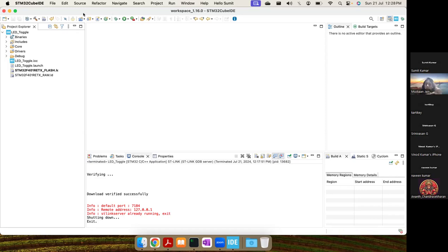Now let us talk about how we're turning it on. We see VCC, the VDD is there. When we put an input to make the PMOS on, the condition for the PMOS to be on is that the gate voltage should be less than the source voltage. Then only your PMOS is on. When your PMOS is on, the current flows from VCC to the pin. It is acting like a pull-up. We do not need any internal pull-up.